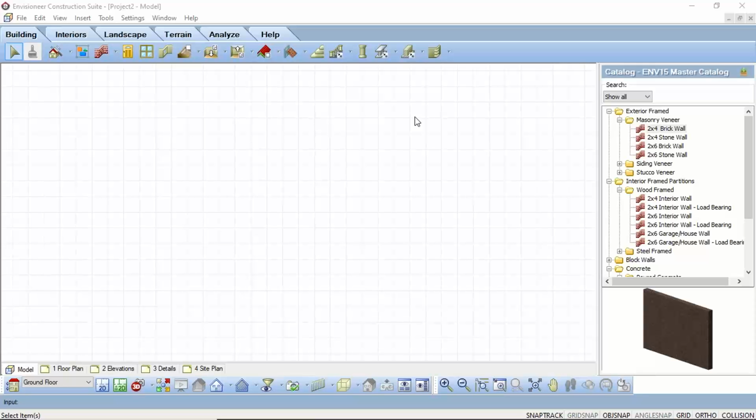First, let's take a look at the actual surface itself, or the surface command. You can use the Surfaces tool to create a custom floor, roof, or ceiling surface. First, you draw the surface by picking the points, then you define its slope. This lets you create a surface of any size, shape, or slope, which can be useful in special or complex construction situations.